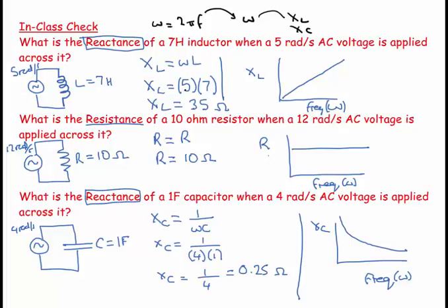I can't just substitute frequency in Hertz for frequency in radians per second. This expression is written as omega because it has to be the frequency in radians per second. You can substitute in 2 pi f for the omega because that's numerically the same value, but you have to get to the radians per second in order for this system to work. So there we have it.